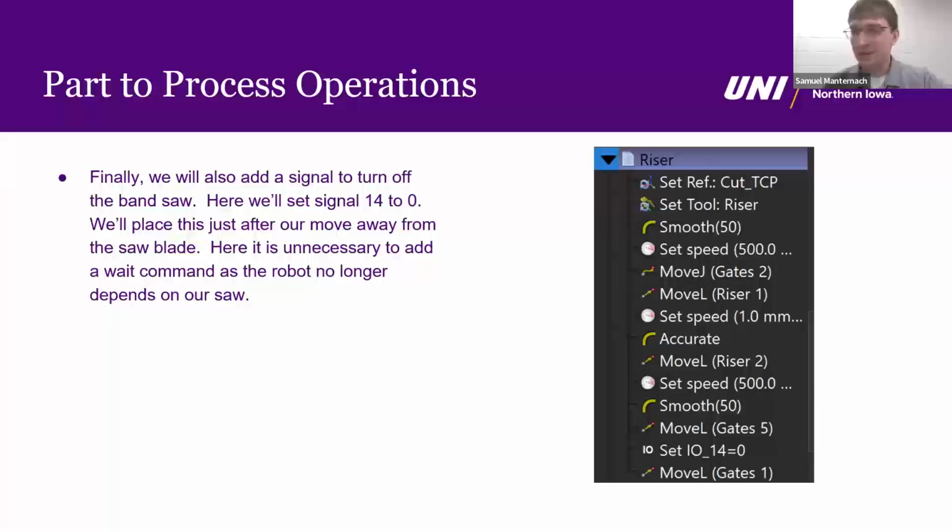So by setting those locations precisely to what we found with those robots, we know there are consistent locations that we're going to be using with the robot, and our robot is going to line up those locations with the targets we're picking here in our offline programming. That way, when we're starting to throw in all of our targets, we know where they are almost every time.